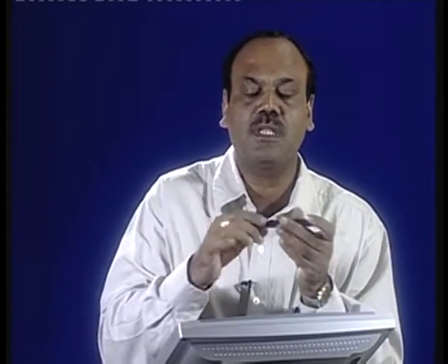Now, as soon as we introduce this particular kind of articulation in a beam wherein it cannot resist any moment, that means we generate an additional equation from this particular condition. That means, if we take the moment of all the forces about that particular point, it is expected that the moment resistance will be 0. Hence, we get another equation based on which we can solve the unknown reactive forces.